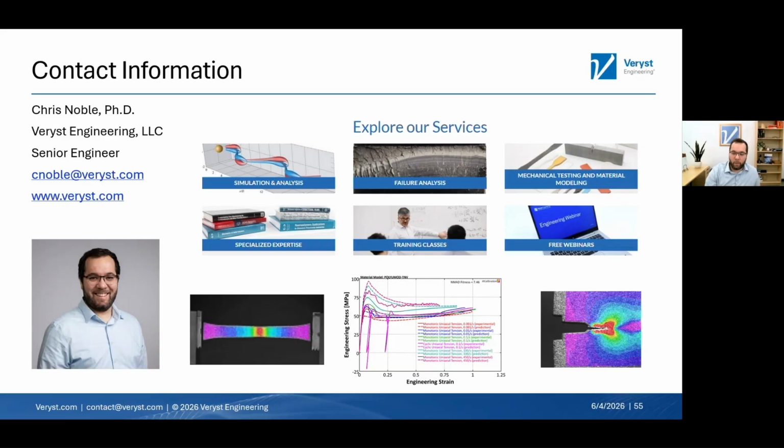Ideally, though, if you can isolate that fabric from your polymer, that is the best way to go. Inverse FEA is not as accurate as testing independently, and it's also a lot more lengthy process to do, both in testing and in your calibration.